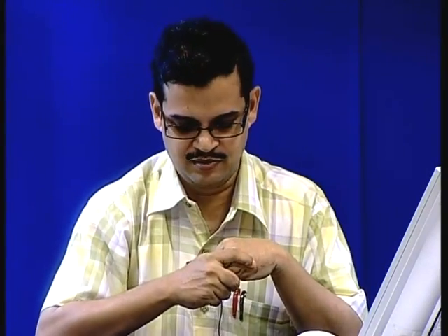With these three rules, the BDD is reduced, okay, and there are some other tricks which we are not going to talk about, like how negations are used. If you have a function and if you have its negation, then rather than creating a BDD for the negated function, you can put a special type of edge which you call a negated edge, right.